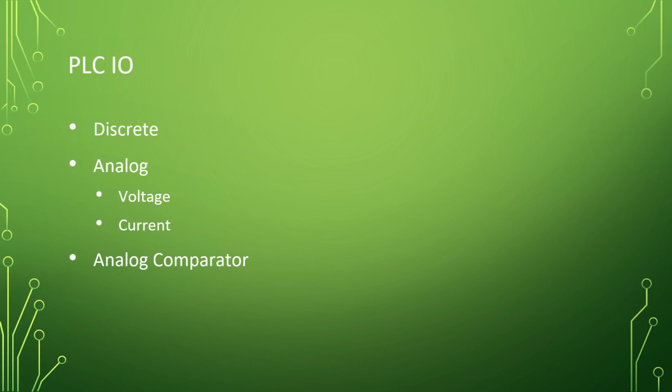discrete or digital inputs. Those would be either a 1 or a 0. So you have a 1 or a 0. That's basically it. That's all you get. And for the most part, discrete handles everything you really truly need: limit switches, push buttons, proximity sensors, temperature sensors can be this way. This is really all you truly need for a simple system.